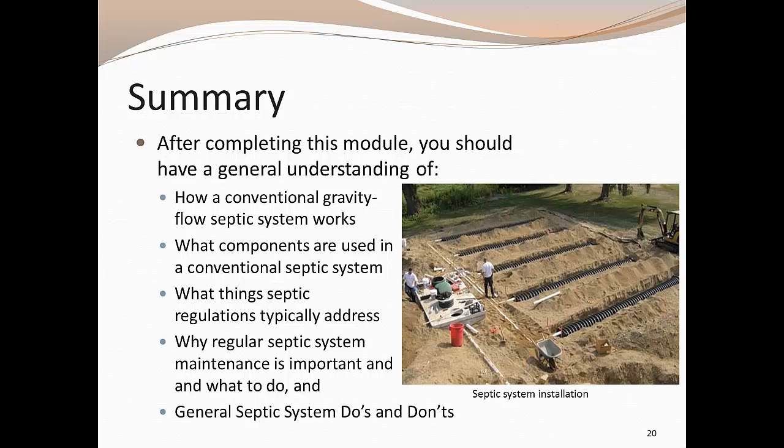It's good practice to have your septic system inspected annually and pumped out at least every 3 to 5 years. If the tank is not checked regularly, the homeowner runs the risk of solids building up in the tank and clogging the treatment area. This can be the leading cause of septic system failure. In some situations, conventional gravity flow septic systems won't work. There are alternative systems available. Each potential septic site and application is unique.